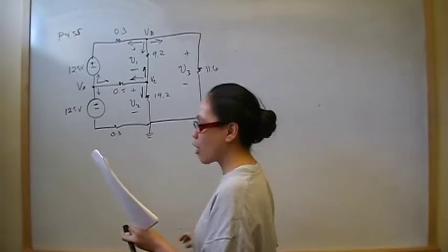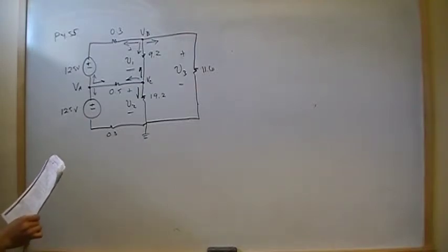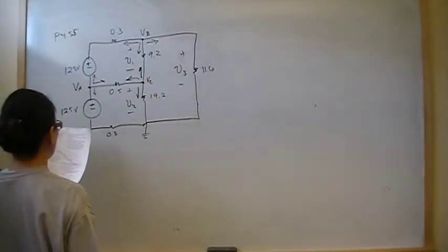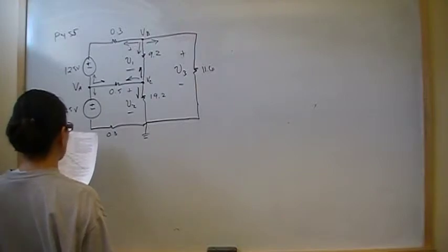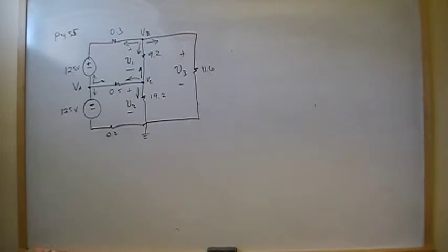So it says the RB branch represents a neutral conductor in the distribution circuit. What adverse effect occurs if the neutral is open? The hint they've given us is to recalculate V1 and V2, and note that appliances or loads designed for use in this circuit would have a nominal voltage rating of 125 volts. So something about the 125 volts is going to be key.